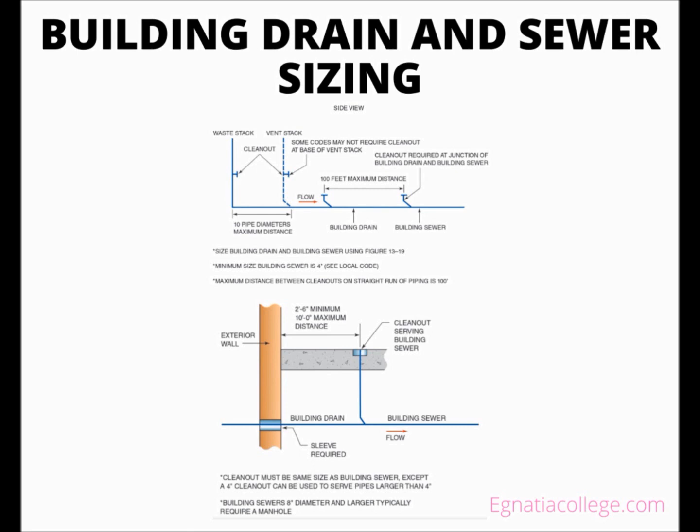The building drain and building sewer are 2 different segments of a system. Some codes may allow different testing requirements for a building sewer than for a building drain, because the sewer is outside the building and can typically be excavated if problems arise in the future. Most codes require a more rigid pipe specification for a building drain than for a building sewer, because it is within the footprint of the building, often making it more difficult to replace.